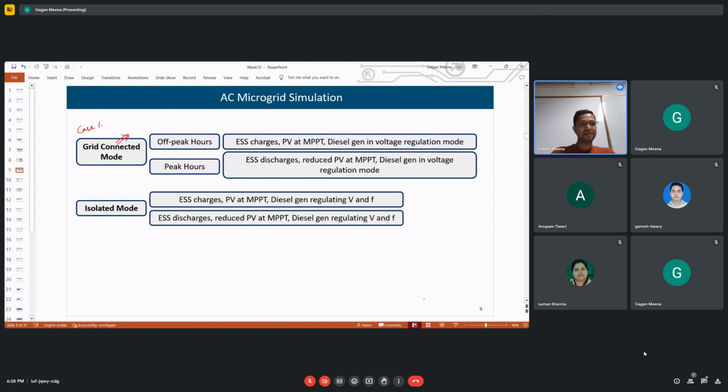Yes. So let's say the load impedance is RL, and the effective impedance seen at the terminals of solar PV is, let's say, RPV. We want to match these two resistances or impedances. So who will do that? The DC-DC converter will help us in two ways.